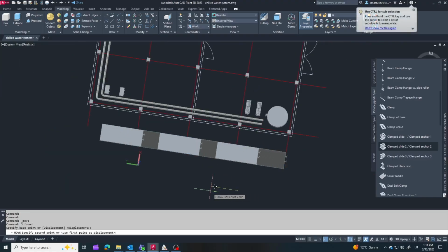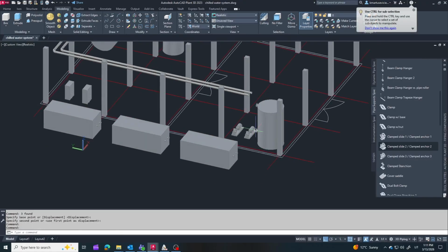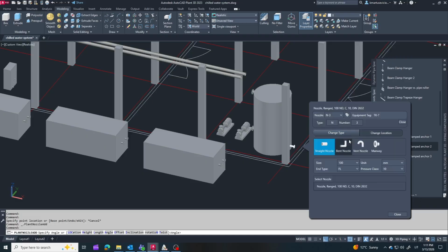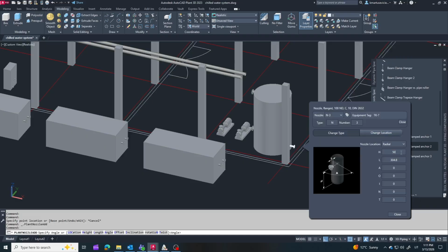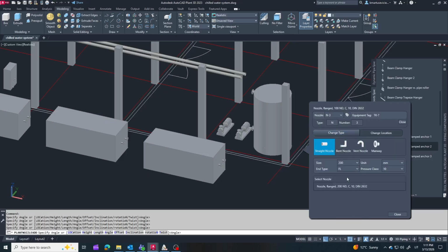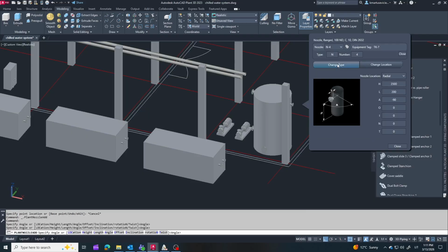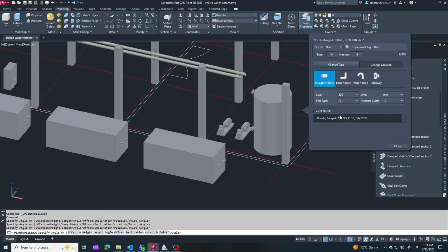When I model something, I often have to move equipment around several times until I find the best position. At the beginning, the layout is usually only approximate. As piping is added, it becomes clearer how much space the pipes need, where supports will be placed, and how maintenance access will work. Because of that, equipment often needs to be shifted, rotated, or spaced differently so the piping runs more naturally and the layout stays practical to build and maintain.